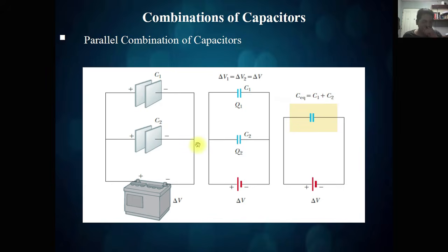Just like what I said a while ago, this parallel combination of capacitors can be converted to a schematic symbol for easier understanding. So this is converted to this symbol, and this capacitor into this circuit symbol. Now, we can simplify capacitors connected in parallel, for example these two capacitors, into a single capacitor. And that capacitor is what we call the equivalent capacitance.